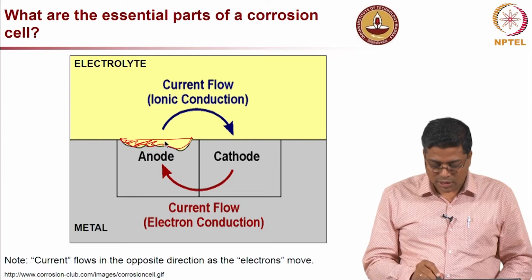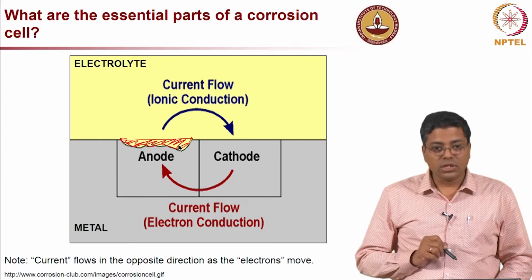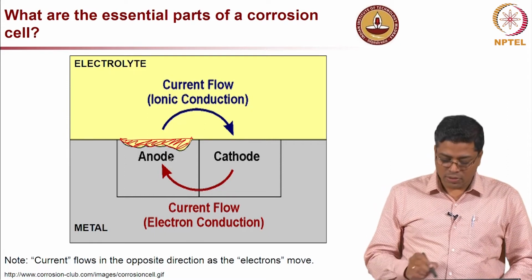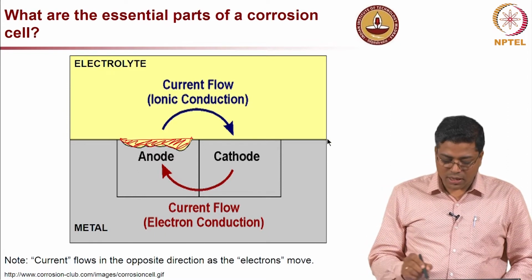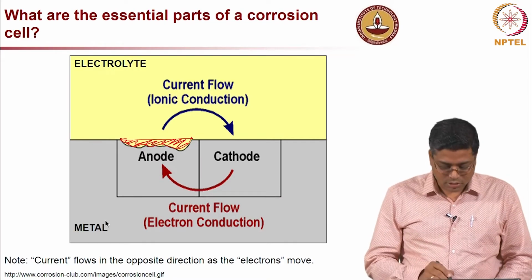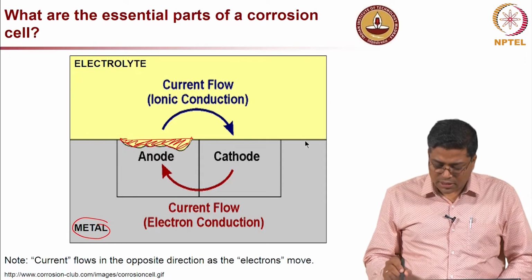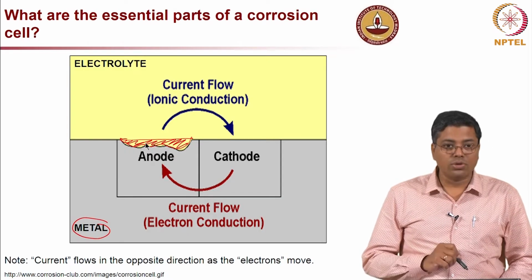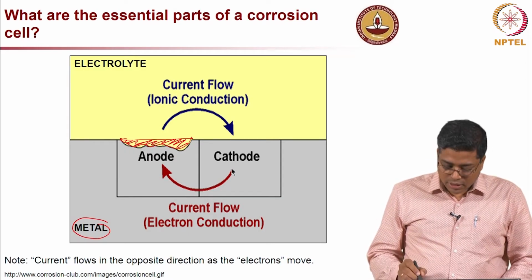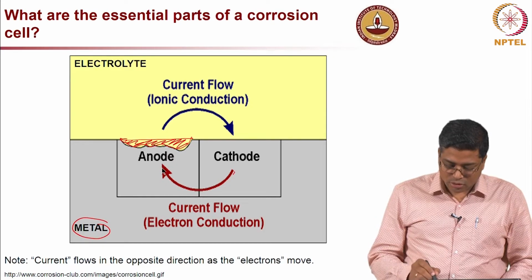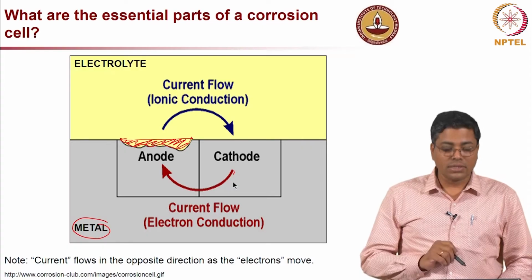So, this much metal has been lost. This region is what is getting corroded, and that we call anode, and the remaining region on the steel, the grey part is the metal, the remaining region helps this anode to corrode, and the electronic charge actually gets passed from the cathode to the anode right through the metal itself.